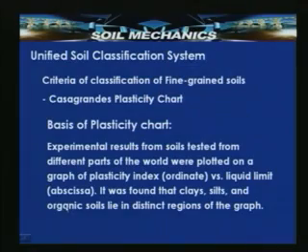Experimental results from soils tested in different parts of the world were plotted on a graph with plasticity index as the ordinate, that is on the y axis, and liquid limit as the abscissa, that is on the x axis. It was found that clays, silts and organic soils lie in distinct regions of the graph.